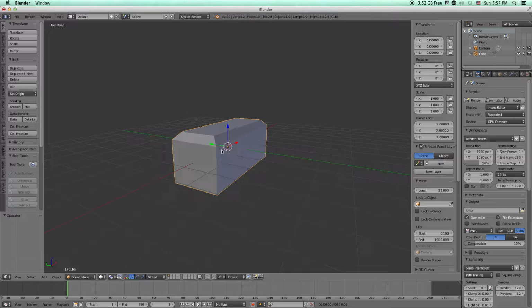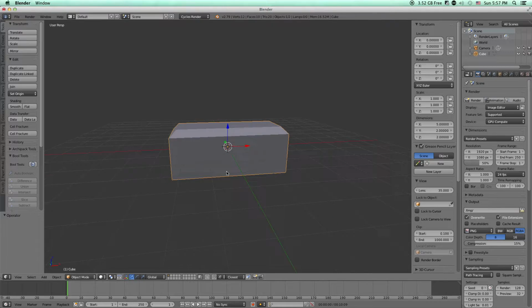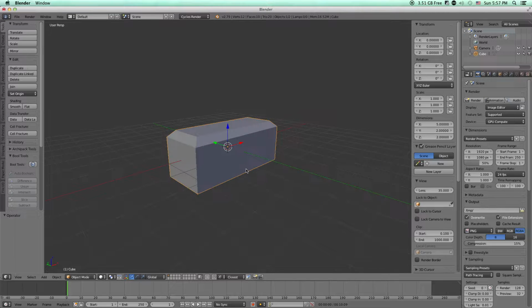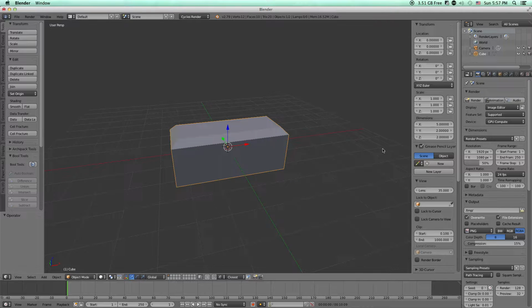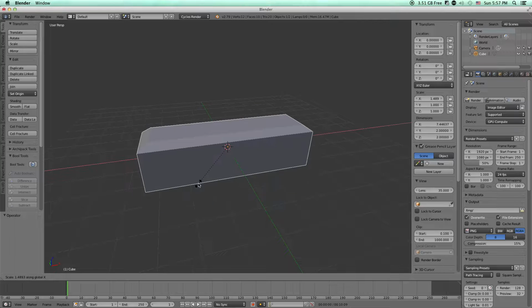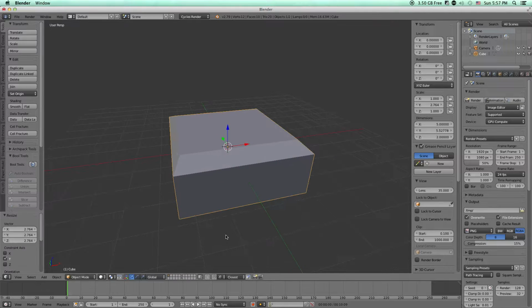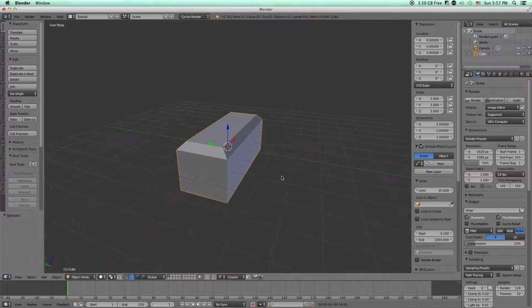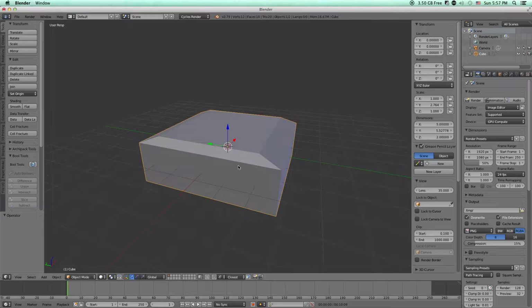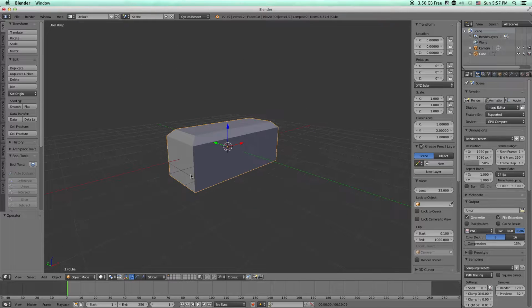So if you don't apply that scale, it's not actually making that object at that rotation or dimensions. So possibly, I think whenever you make an STL, now it will kind of ignore the scale, I believe. But just in case, if you scaled it this way, but it came out in your 3D printer software like this, be sure to apply that scale so that it makes sure that it comes out like this.